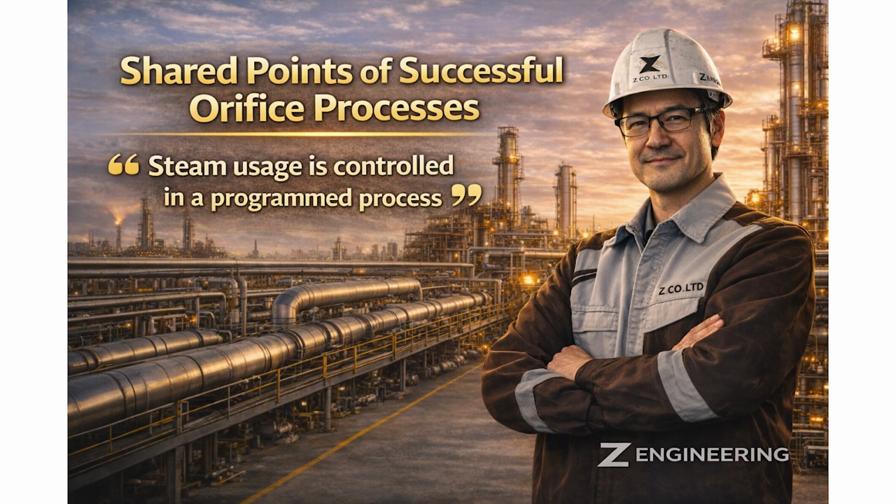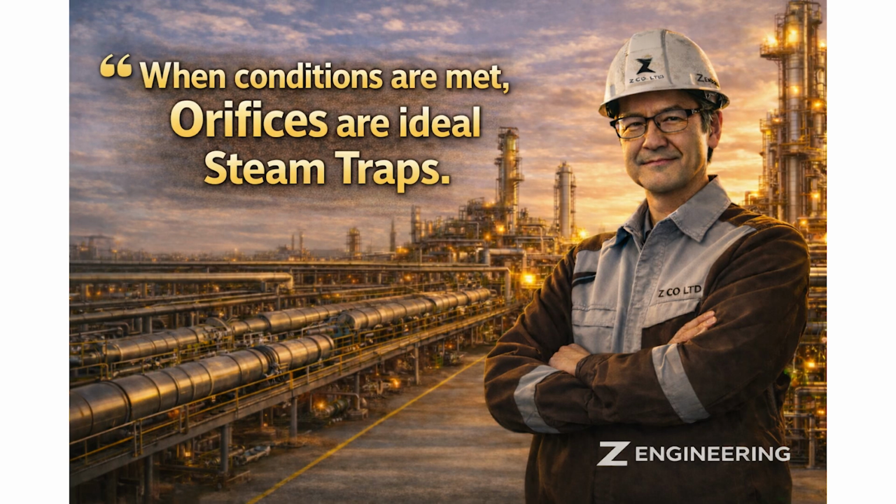The conditions for an orifice trap are simple. The process must have programmed temperature control. Steam consumption must remain predictable, within the design range, and differential pressure must remain stable. Whether an orifice trap works is determined by the steam conditions of the heat exchanger. That is why, when we visit a factory, we focus only on those conditions.